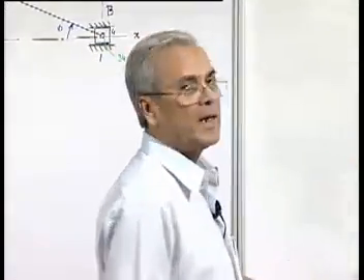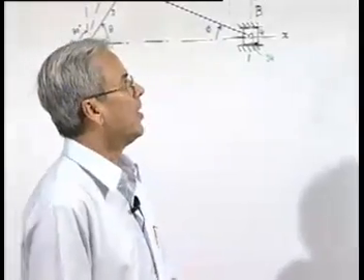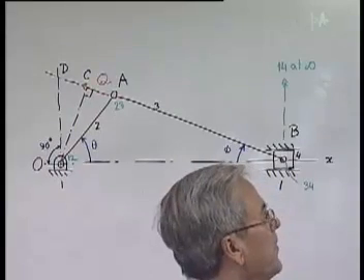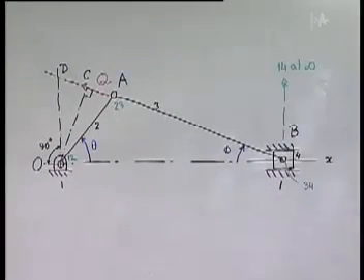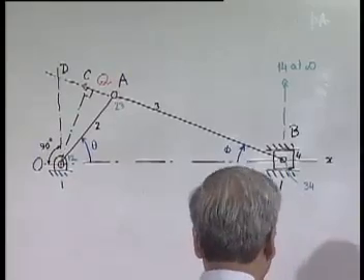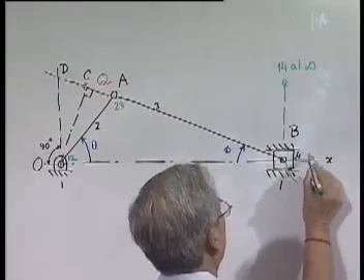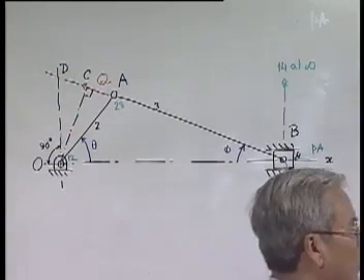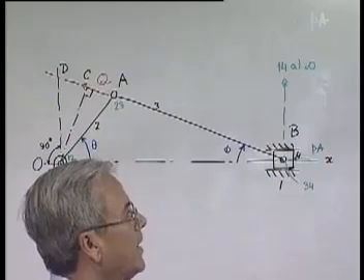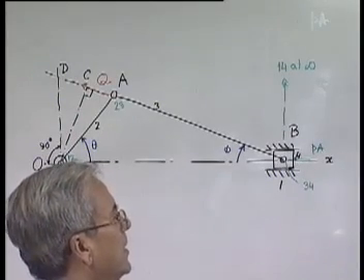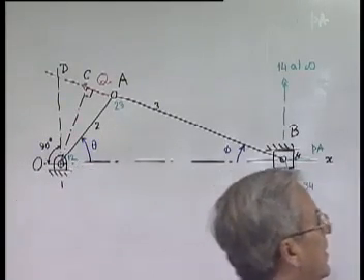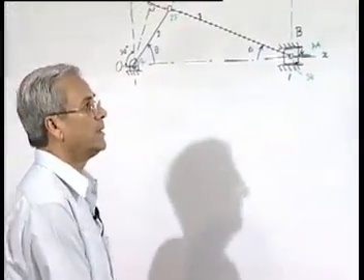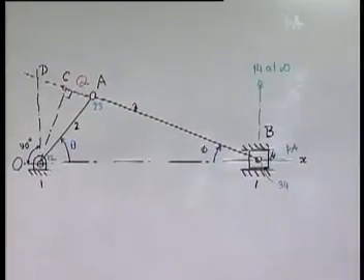The turning moment expression we have got is a function of theta and phi, because the gas pressure acting on the cylinder is also a function of theta, as you will see. However, it may be desirable to express the turning moment completely in terms of one variable only, theta, because theta and phi are dependent. We can do it in this particular way.